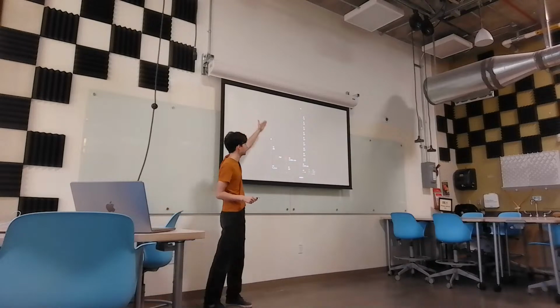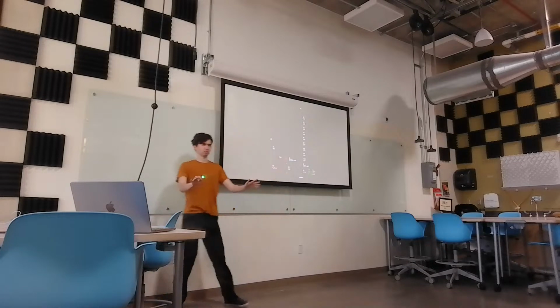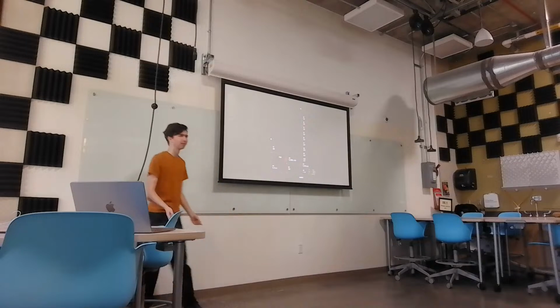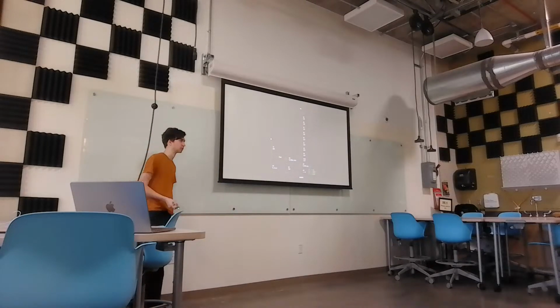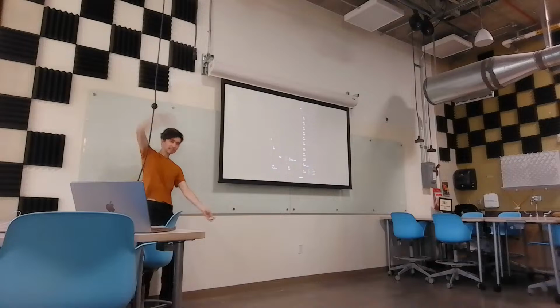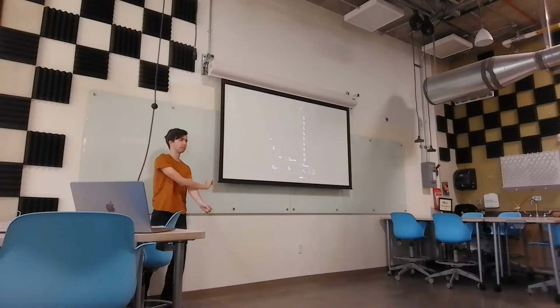We've got all these LEDs in series. You might be thinking, well, I've never seen that before. Why not do them in parallel? That's how everything else in the world works. Well, here's my thought process. I've got almost 100 volts coming out of this one battery. Why would I want to regulate that down to like 3 volts for a bunch of LEDs in parallel?